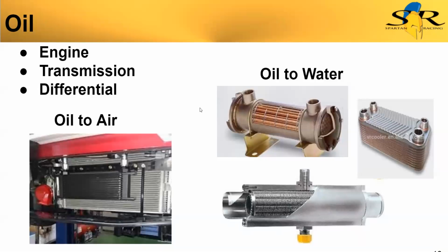Would it be redundant, or do you think it would give some performance improvement? I know it depends on the radiator. It kind of depends, and that's a good question. To segue out of automobiles, they do that kind of intermediate heat exchanger a lot in HVAC systems and nuclear power plants and things like that, where they really need to maintain the purity of the water and keep the system separate. So in doing that, I think it would be a little bit redundant.